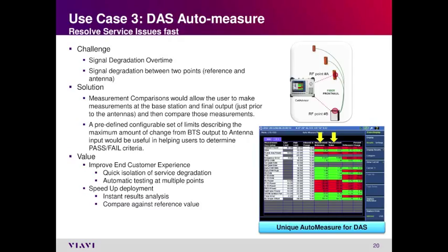The second thing it helps with is that, let's say you come back in 6 months and you have measured the RF environment at a certain point, and then you can go back to your reference file and compare how far off I am. You can configure the level of acceptance, right? And if you come back after 6 months, you can see if it's 3 dB off or 4 dB off, or within the same level. So it helps you quickly identify any problem issues. You can go back and say, it used to be fine, working perfectly, now I have a problem, rather than going all around trying to identify and isolate each and every problem. So you can isolate each and every antenna point separately rather than walking it and doing a deep analysis.